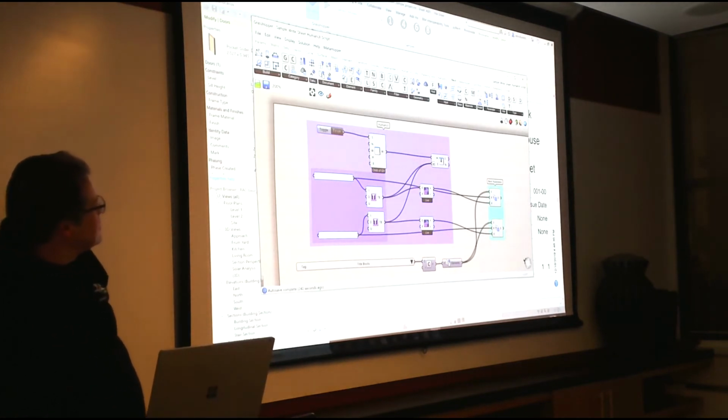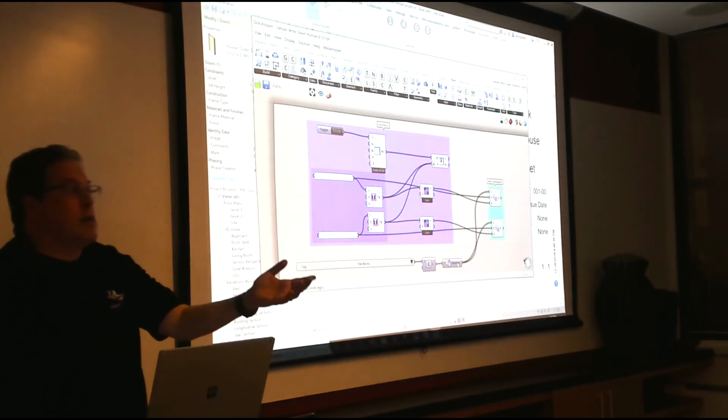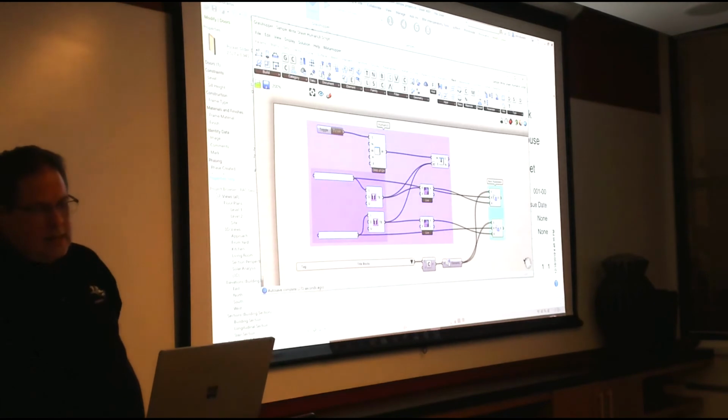Yeah. But so here's the dialog box, right? Here's the displayer. So what I'm going to do is create 2 text boxes. I'm going to call them drawn by and checked by, and I'm going to watch their values, just like we do in normal UI. Then I'm going to find all the title blocks in the model, find all their element IDs across all families. Now I could be smarter and do it by certain families, but in all families, I'm going to pump the element ID, and I'm going to use this key, drawn by and checked by, and change their values based on how the dialog box updates values. So that's all there is to it.